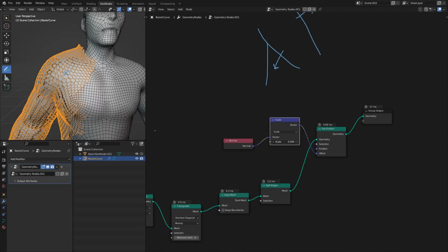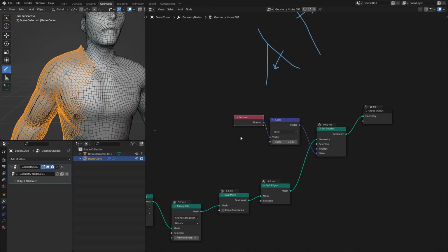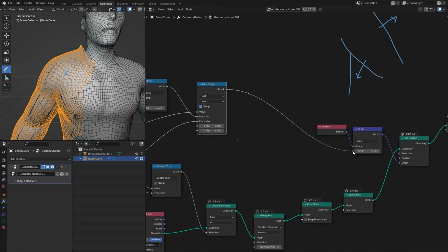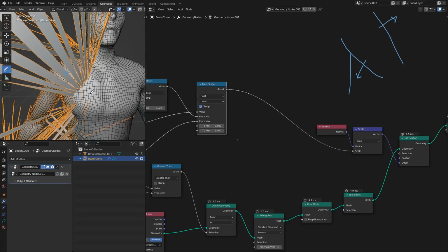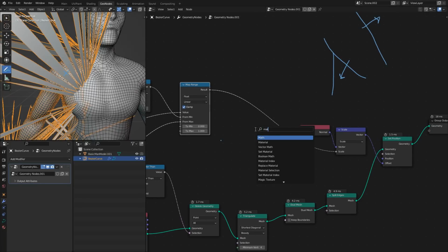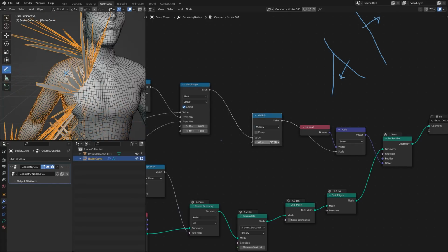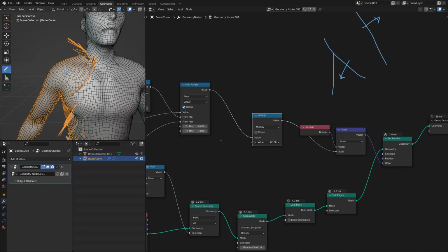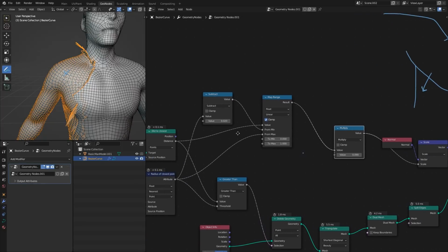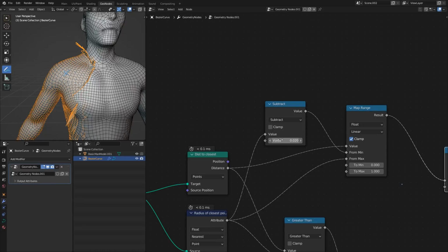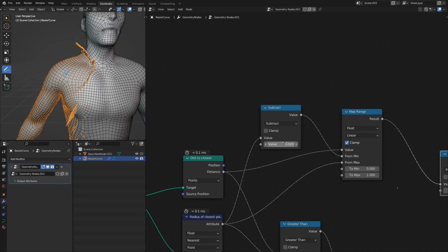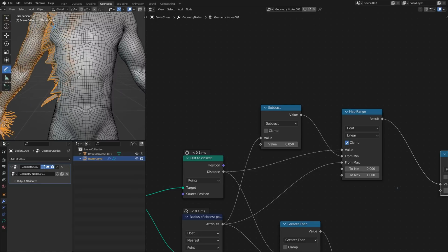See how we're pushing everything? And now if I plug the map, which currently goes 0 to 1, into this scaling through a math node, just so we can control that, I can now adjust at the end over here. You can see how they're moving, and if I change this amount, which is where we start to remap from 0 to 1, we will see that now we're pushing them from a bigger distance away.